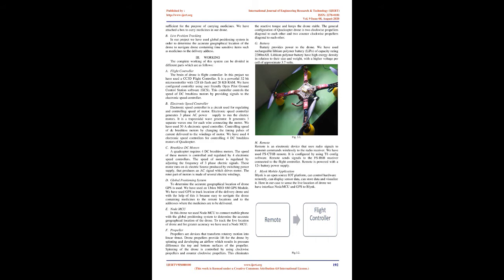Electronic speed controller is a circuit used for regulating and controlling the speed of a motor. It generates a three-phase AC power supply to run the electric motors. It is a trapezoidal wave generator. It generates three separate waves, one for each wire connecting the motor.